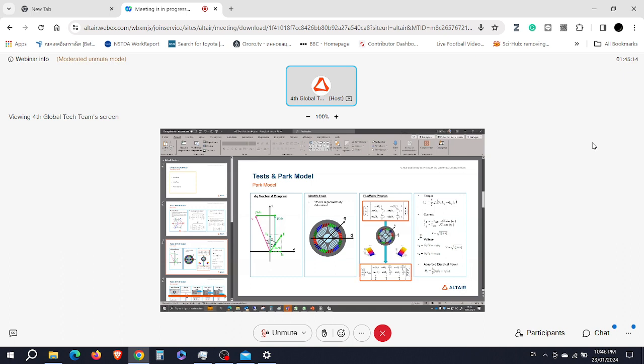We can compute VD, VQ, then the voltage for each VD, VQ, and ID, IQ. Then we have all we need to compute the joule losses, the absorbed power, the mechanical torque, and so on. So this is the Park model to make computation easier.